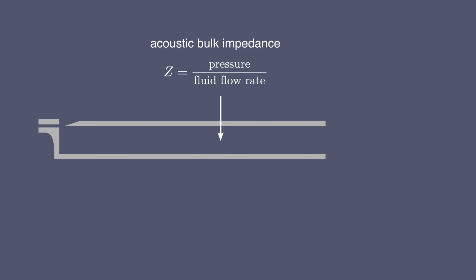The specific impedance inside the pipe is about 413 rayls. That's the acoustic impedance of air. The specific impedance outside the pipe is also about 413 rayls, the acoustic impedance of air. So where's the impedance mismatch? Well, you can define the impedances so that we have the correct reflection. We can define a bulk impedance in the pipe and a radiation impedance at the opening.